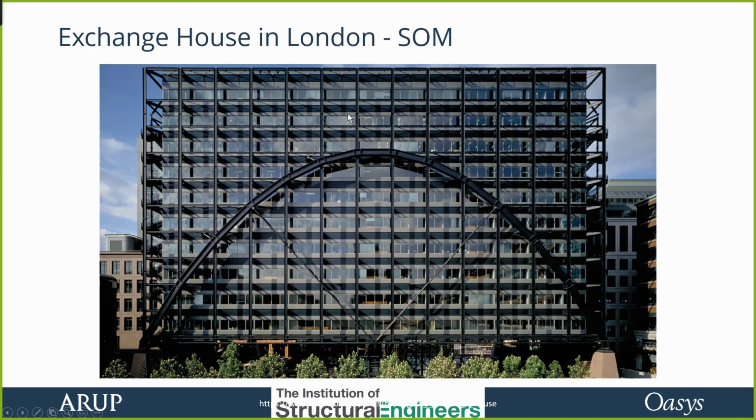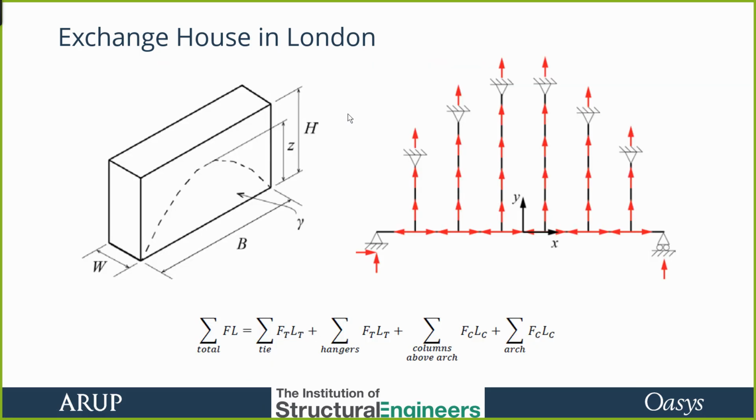So they used Maxwell's theorem to look at, in this case, do it by hand, looking at just the tension elements. And if you're up with the calculus, you could put that in as a formula, and then work out the minimum from there straight off. If you're doing it by computer, you could just build a model and just vary the height to give you the ideal option. Yeah. Or calculator, depends how you go about it.